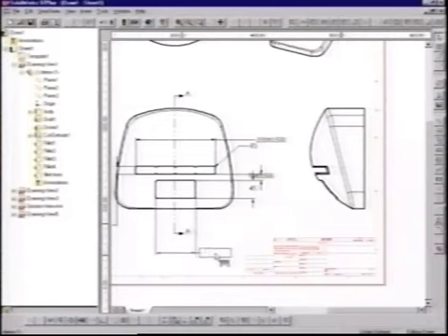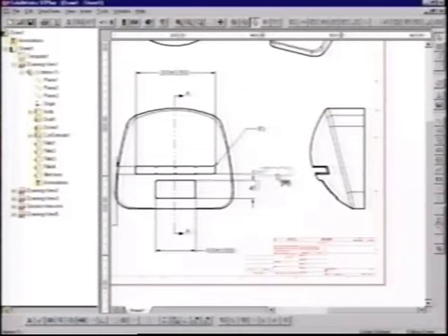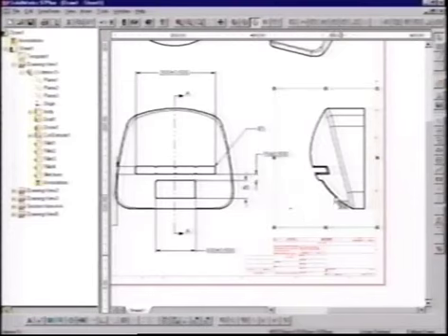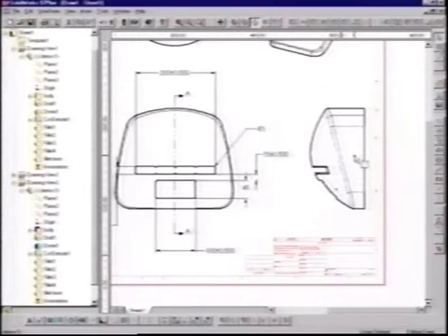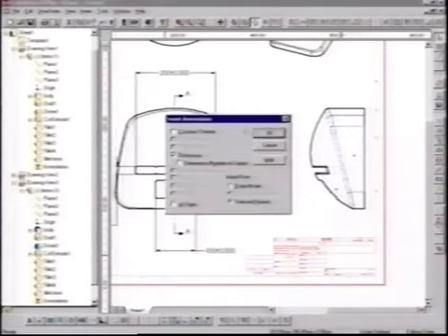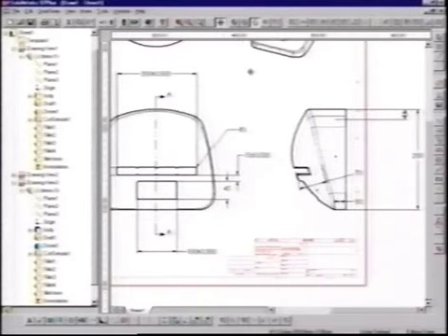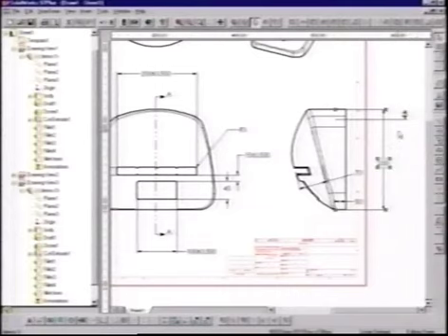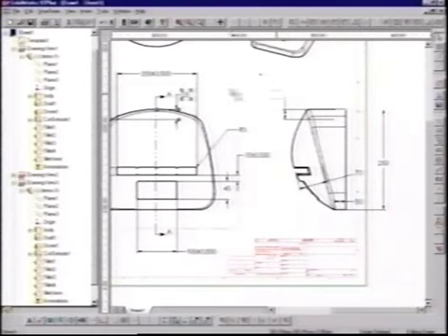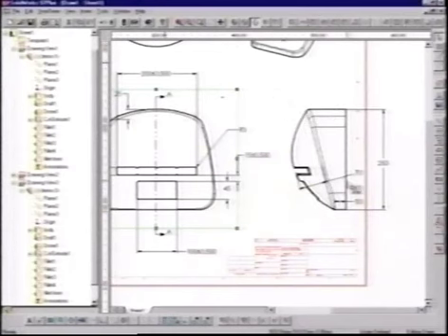So in this particular case, he's shown the dimensions for that display cutout that he dragged and dropped from the previous assembly. Joe has the ability to drag the dimensions around and modify the values or delete them without any special commands because, as you see here in SOLIDWORKS, it's just standard Windows interaction. As I'm speaking, Joe's going to continue by dragging the dimensions around and showing you dimensions in other views. To move dimensions from one view to another, again, it's simply a drag and drop from one place to another.